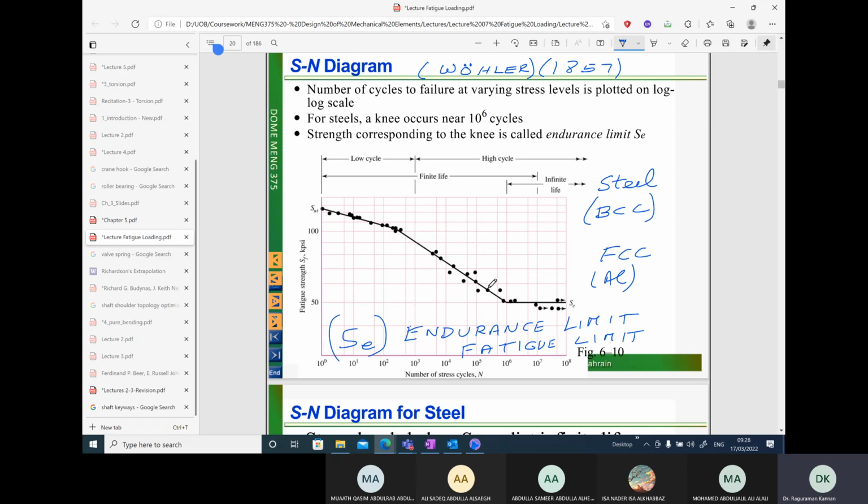In this region, we have to come up with an empirical relationship by the curve fitting method, between the amplitude of stress for completely reversed loading and the number of cycles to failure. There is another equation which we will go through here as well.